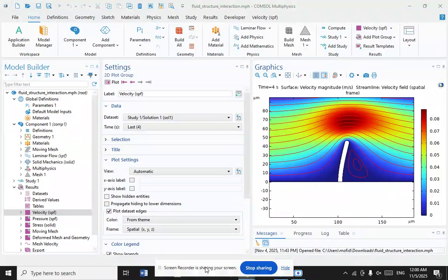The fixed point problem can be solved with fixed point iterations, also called block Gauss-Seidel iterations, which means that the flow problem and the structural problem are solved successively until the change is smaller than the convergence criterion. However, the iterations converge slowly, if at all, especially when the interaction between the fluid and the structure is strong due to the high fluid structure density ratio or the incompressibility of the fluid.